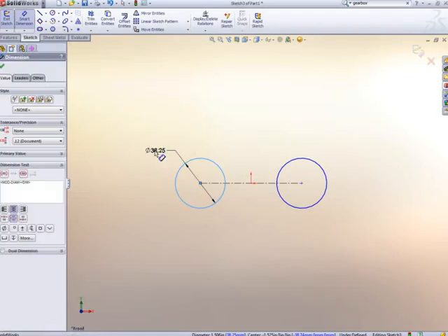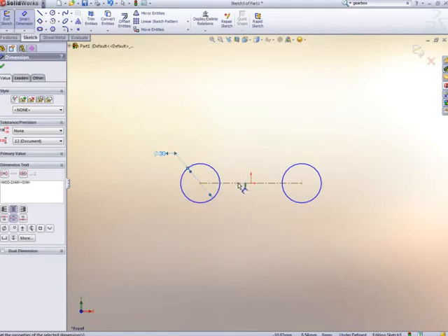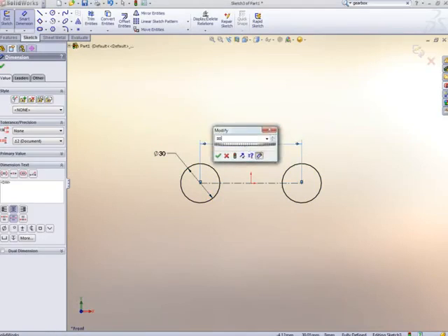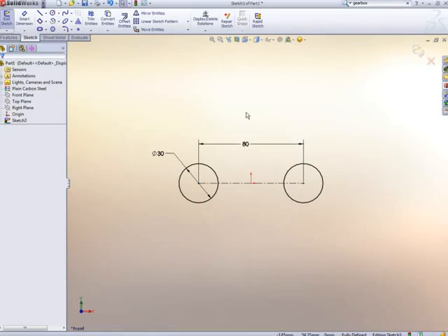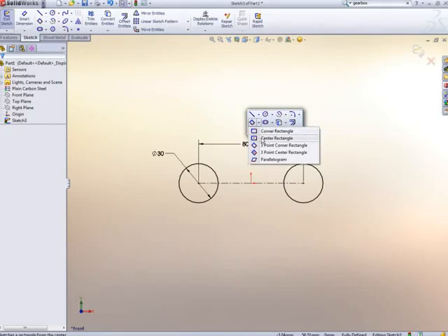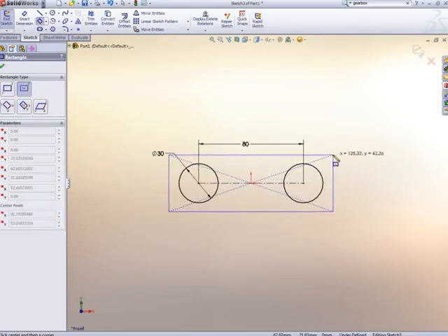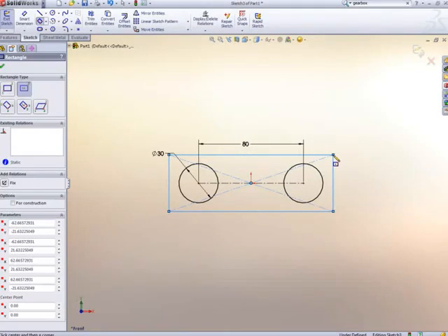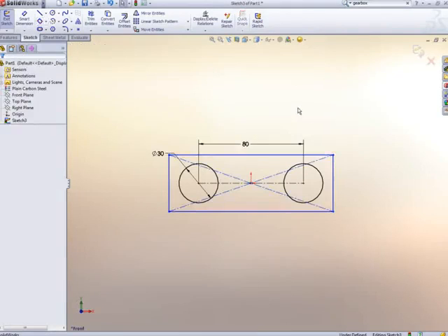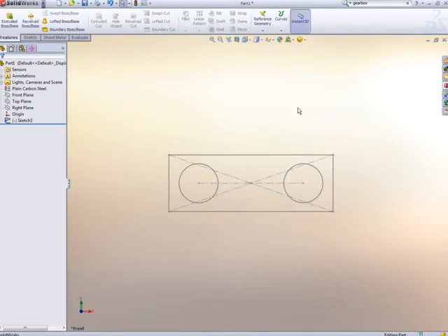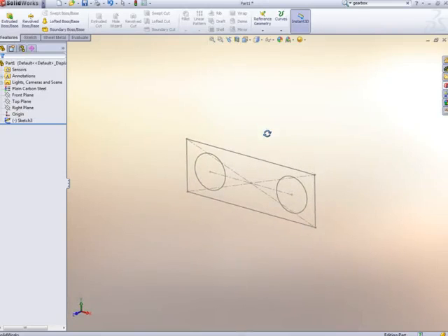And of course, every engineer lacks precision, so let's add some sizes. Easily done. And finally, we'll add a box around these holes. With a large set of sketch options, such as center point rectangle, we can build the exact shape with minimal effort. And if it's a concept design, you may not want to size everything at this stage. The choice is yours. The middle mouse button rotates the view and is always on, so you don't have to move the mouse or press any buttons on the keyboard.